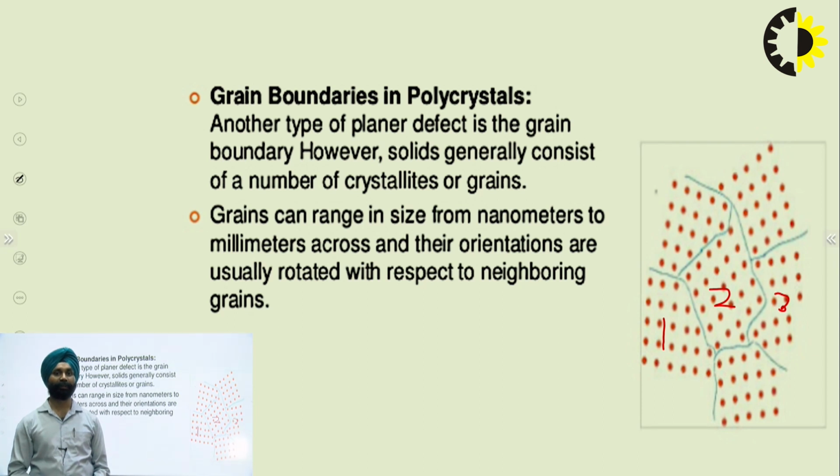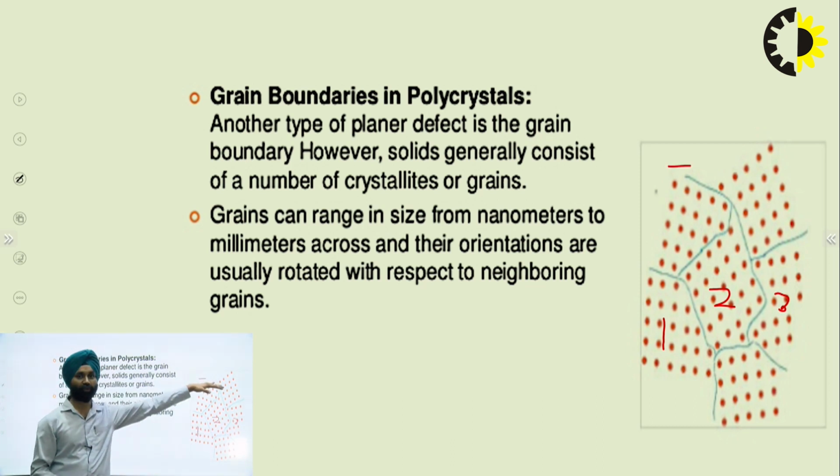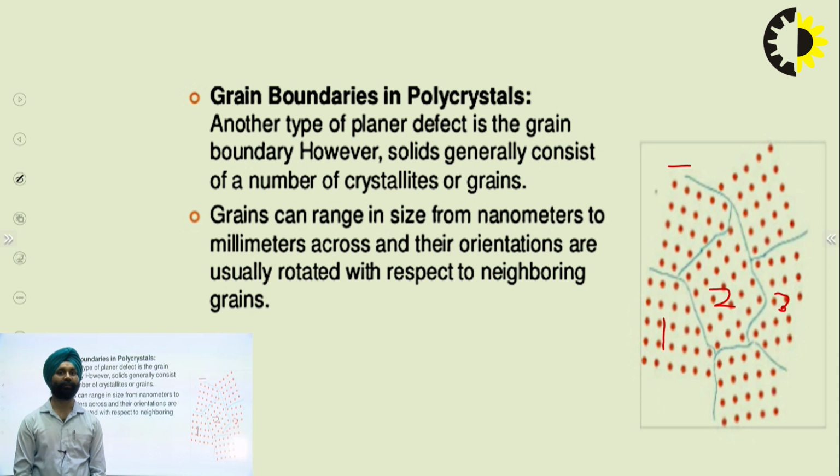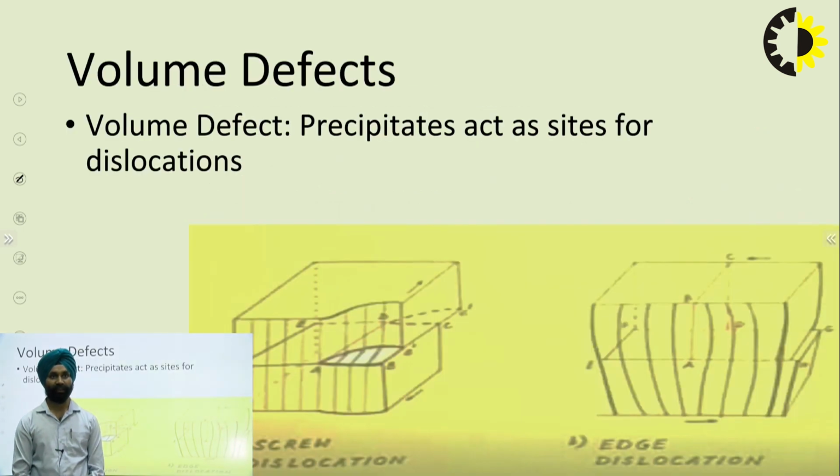Also, if we prepare the next step, which is epitaxy, over this one, the crystal grown over this grain boundary will not be as smooth as we want. So depending upon this one, there will be the grain boundary and the twinning effect.